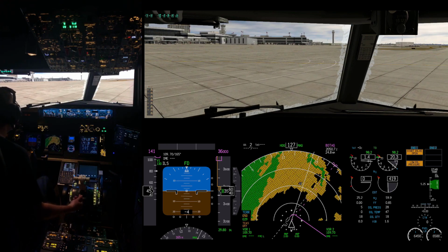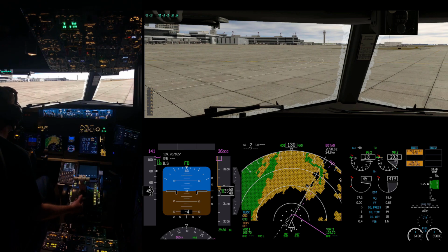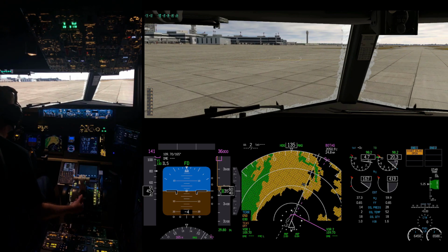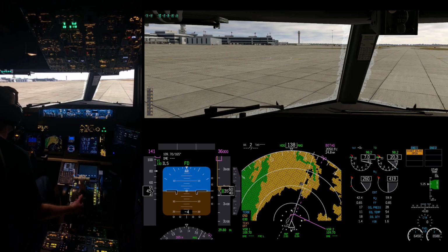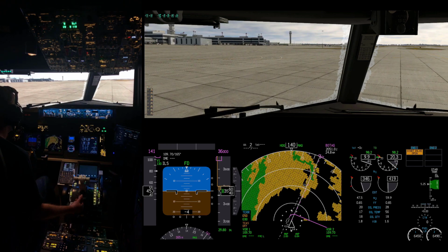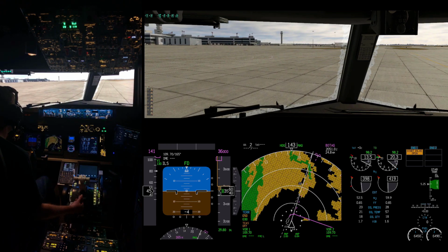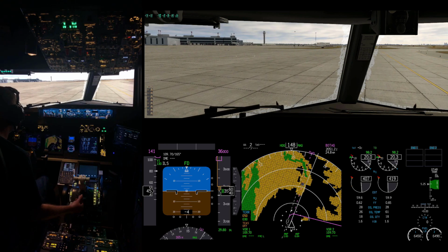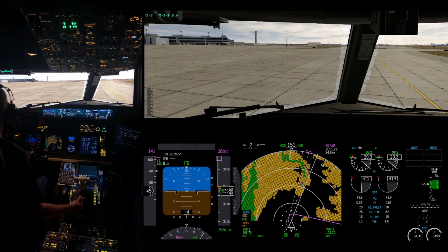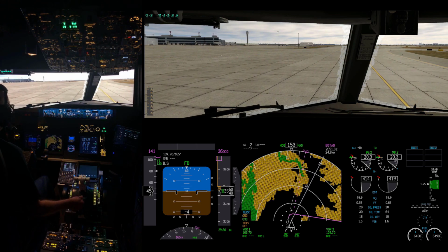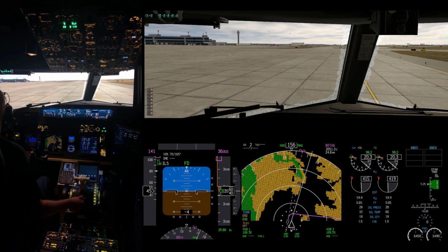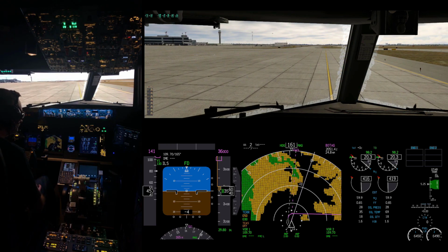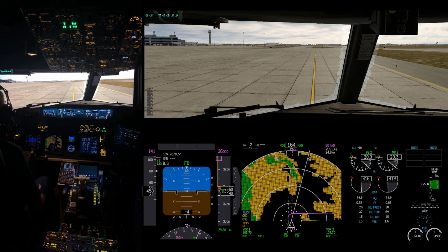We add fuel. Exhaust gas temperature, and 1 starts to move. And 54% switches to off. 246. Engine number 1 started good. Now we'll wait for him to finish the pushback, and then we can get taxiing to 17 left.